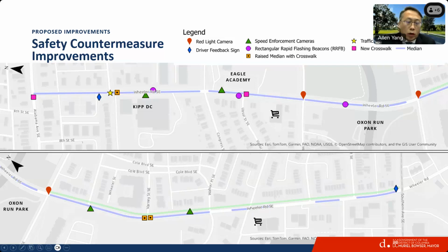We have done a traffic signal warrant study. The volume and pedestrian crossing safety data justify this new signal. The signal will provide much needed protection for safety and corridor coordination and progression. New crosswalks are provided at strategic locations, such as the Upsall Street, as I mentioned. Another new crosswalk will be provided on Alabama Avenue at the west side. So we have performed our analysis. We're sure with these improvements, the crashes will be reduced significantly.